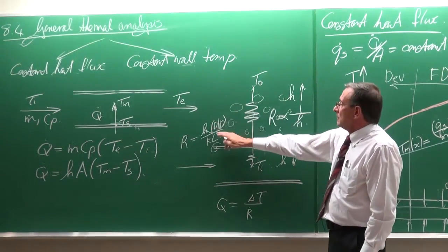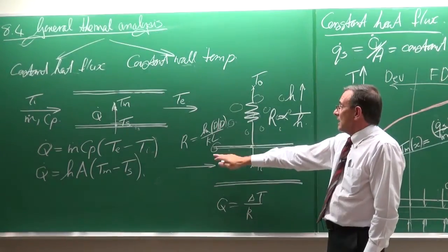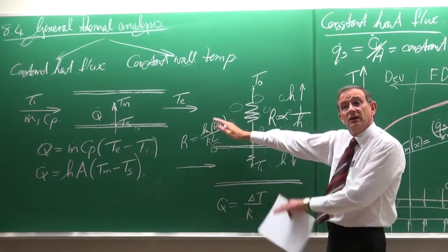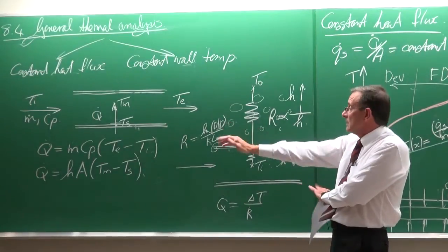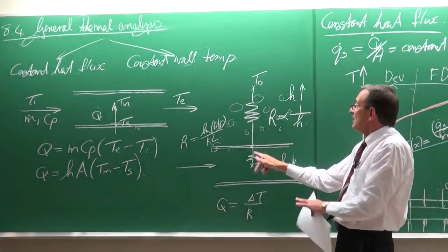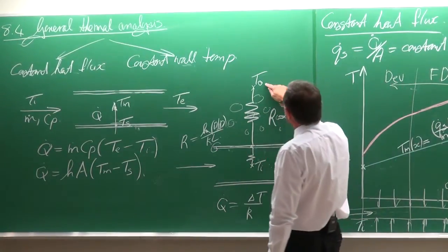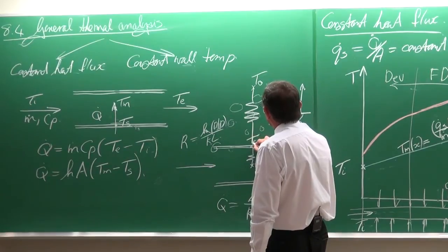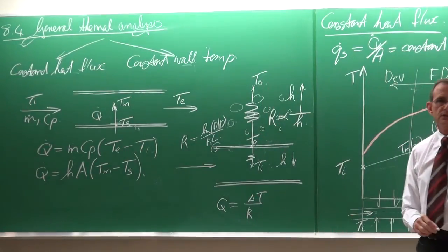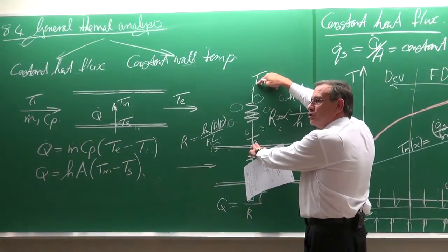And the ln of those two would normally be almost 1. And that would also be very high. And we're going to do calculations like that. So this resistance is also negligible. So you will find, if you do many calculations like this, that this temperature is equal to that temperature for all practical purposes. Okay? And that represents the case of a constant wall temperature.